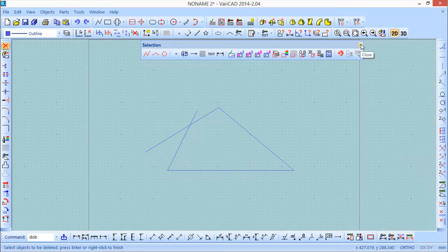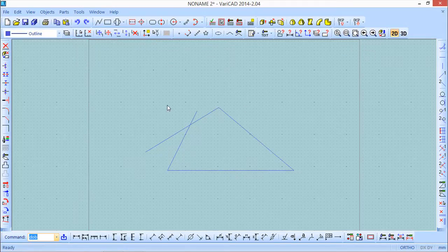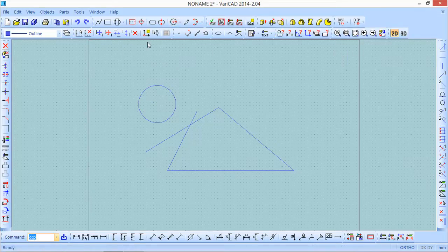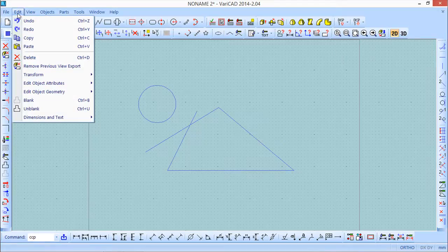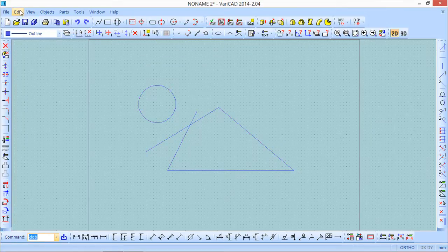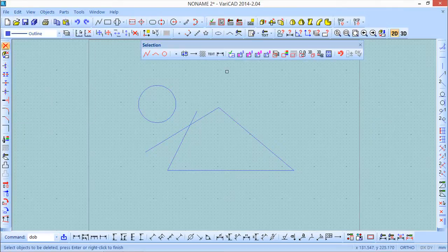In this case I have only considered one polyline. I will draw another kind of object, and I will go again to menu edit, delete, and now I can click. I will press escape, or if I go again there and do a selection by window, whatever you want, I can select both.